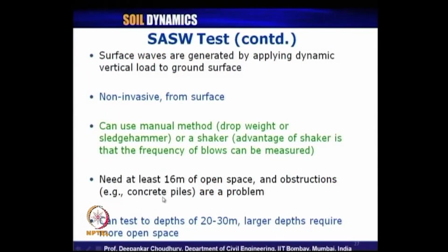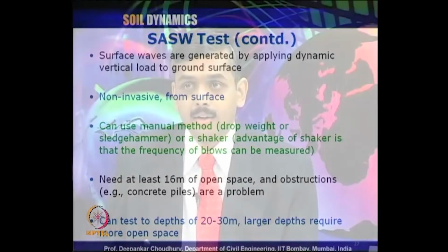So, be aware of these points: that is how to identify a very high value of Vs. Sometimes even a very low value of Vs will help you identify a sandwich of thin layers. What does it mean? Suppose you have a continuous, pretty thick layer of some stiffness, and below that another similar stiff material, following the criterion we mentioned, that the upper layer stiffness is lower than the lower layer stiffness.